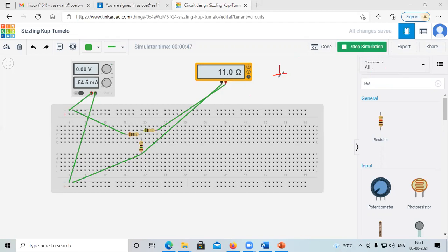So one voltage source, which is our VTH, then the value of resistance RTH, and in between these two terminals, first we removed the resistance, that is RL. The value of RL is 20. The value of RTH is 11, and the value of VTH is 30. Okay, now we make another circuit like this, and we will calculate the current IL.